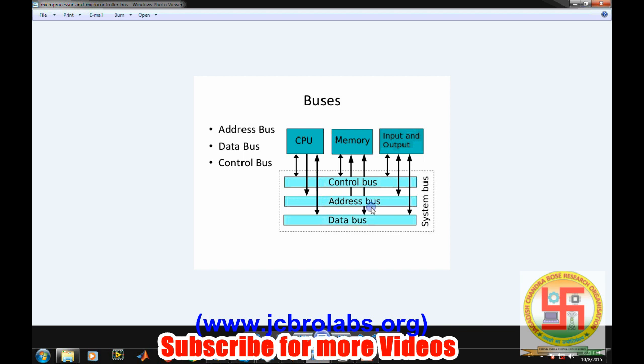But the address bus and data bus need to be understood in detail. The address bus and data bus are the wires used to transfer data from one area of the microcontroller to another area. Like there is one register, the accumulator, and we want to move the data from the accumulator to some other register of the microcontroller, then the data bus is used.